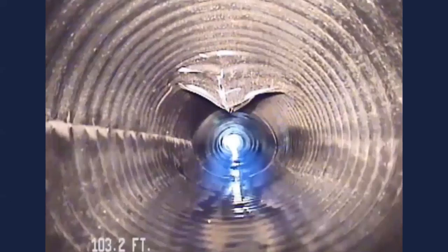So obviously there was an issue with this pipe, and after getting to the end of the line, they went back with their light and camera, and they saw what the issue was. Now, this is an image from the video that shows the top of the pipe smashed by something. Now, in this case, there was a large boulder in the backfill material, and as they were compacting above the pipe, this large rock damaged the plastic pipe and came through and punctured it.